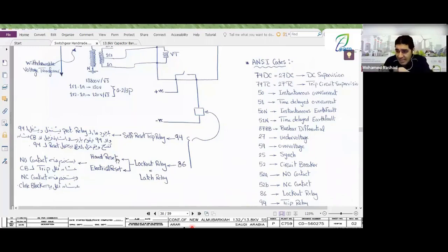Either by a hand reset, where you manually come and reset it. There is a button on its face that you press mechanically to reset it, meaning you move the contact away from this magnet. Or by an electrical reset, which means you have 2 coils. These 2 coils have something like a balance between them. So when one is activated, it tilts the balance like this, so it keeps holding the balance in this position. To reset it, you need to apply a current to this coil to create a repelling force and reverse the position again. This is what we call an electrical reset.